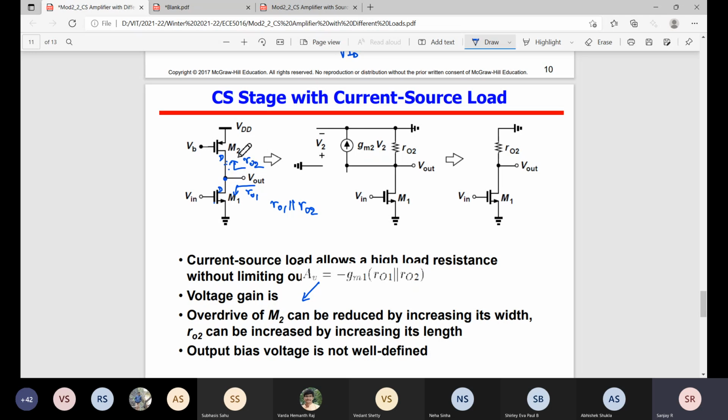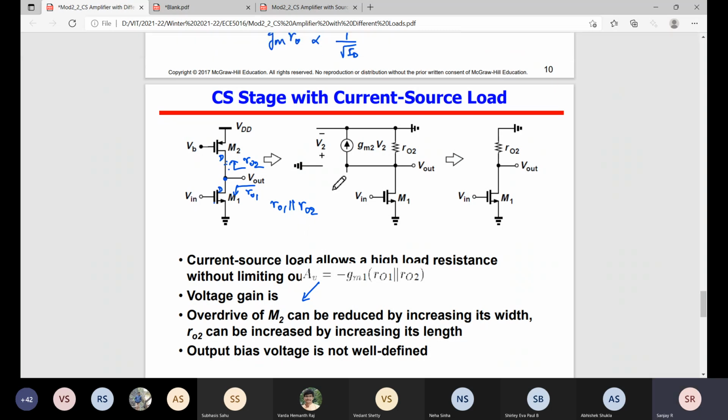But in the common source amplifier, we are going to do the next lab, we are going to do this experiment only. I will tell you how to fix this node voltage in the lab without using common mode feedback. I will tell you some simple idea, because we need to simulate this amplifier. To simulate this amplifier, the DC at every node should be constant. It should not vary; it should be fixed to some known value. For that I will apply a simple technique. I will discuss it in the lab hours. Fine. Anyway, you need to remember, whenever you connect NMOS and PMOS, we need a common mode feedback circuit, or some feedback should stabilize the voltage at that node. Is it clear what I'm saying?